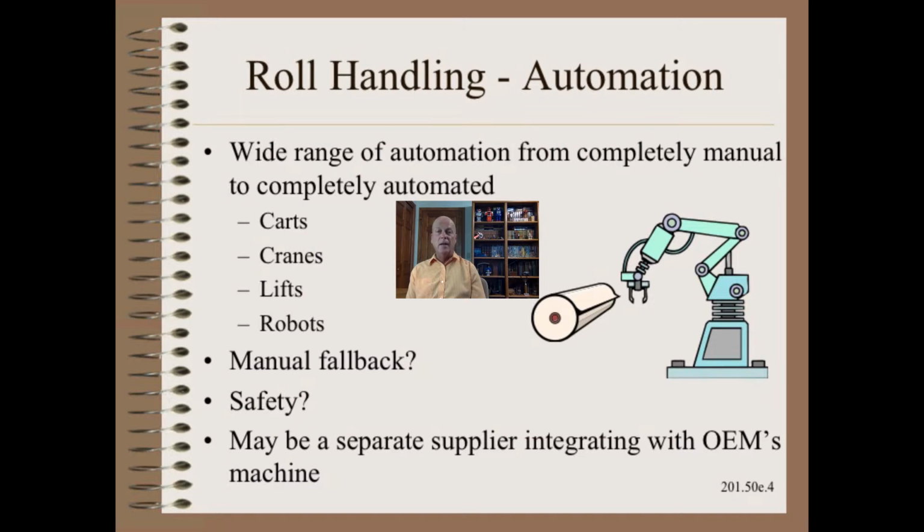The first is reliability. If you have an operator get sick on a totally manual system, he or she could be replaced in minutes. However, if you have a crane or a robot get sick, your entire production could be down for hours or days. Unfortunately, complex machinery has many more failure modes. Also, custom automation has a much higher failure rate than, say, robots that have been tested and field proven with hundreds, if not thousands, of nearly identical models before you order yours.